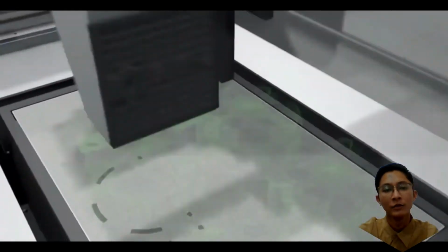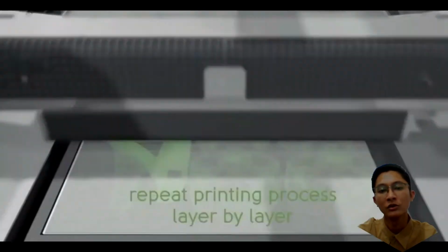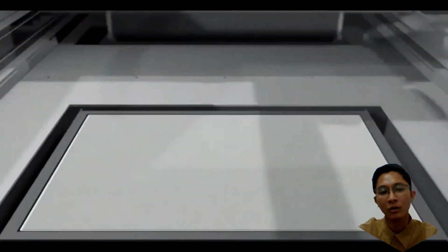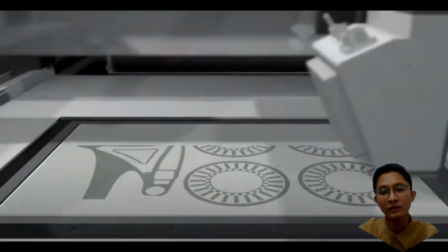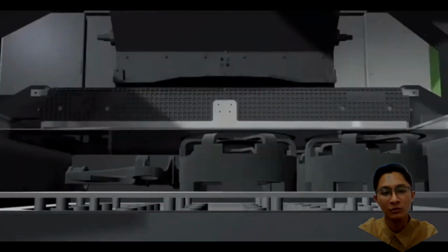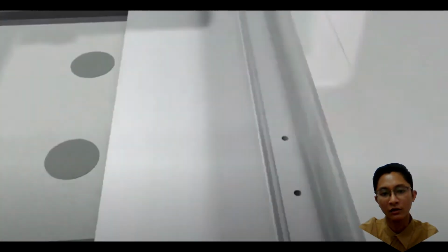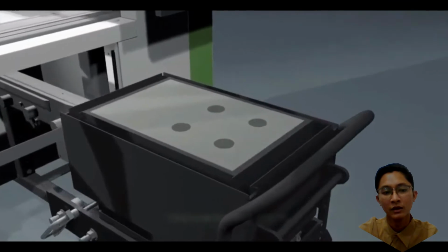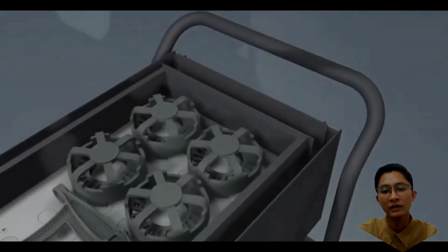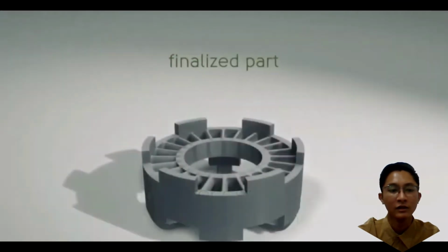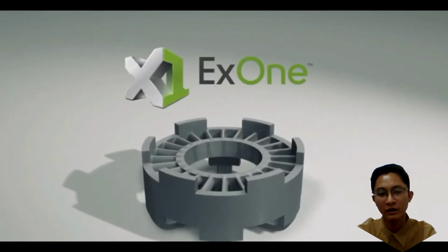Material is jetted onto the build surface or platform where it solidifies and the model is built layer by layer. Material is deposited from a nozzle which moves horizontally across the build platform. The material layers are then cured or hardened using an ultraviolet process.